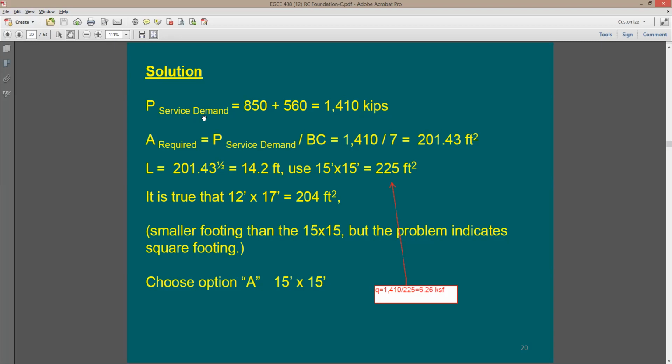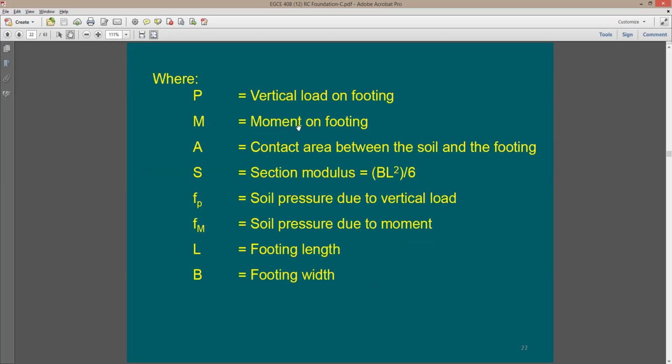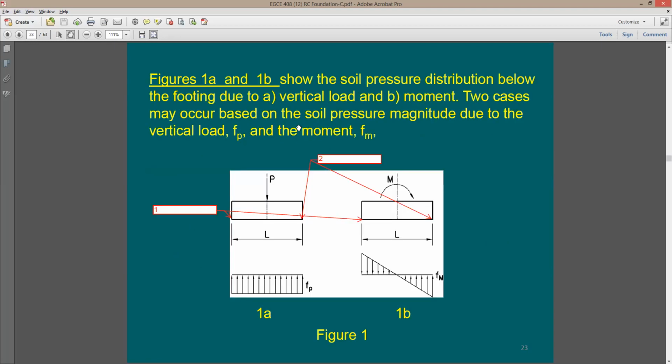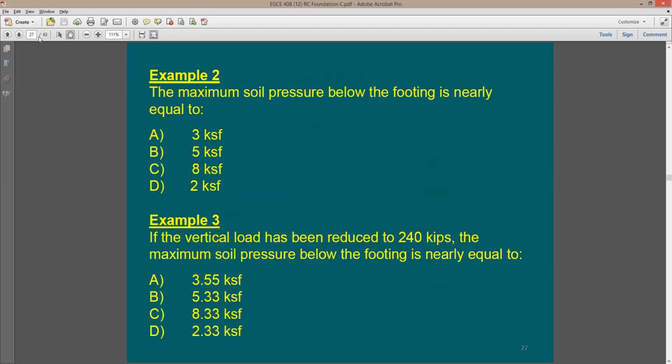After this, you need to design the footing, design the reinforcing, do one-way shear check, and do punching shear check, or whatever is needed from you. I'm sure that you guys have seen this before, right? Yeah, absolutely. It's all recorded. I expect that you guys are going to be reading this again and doing these problems. So this slide set, 63 slides, you really need to go through it and understand each little thing in there and be able to solve with it.